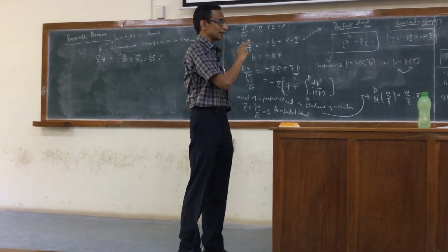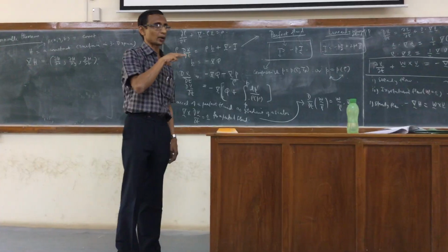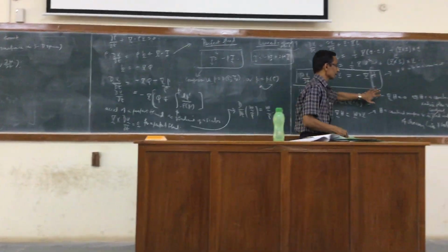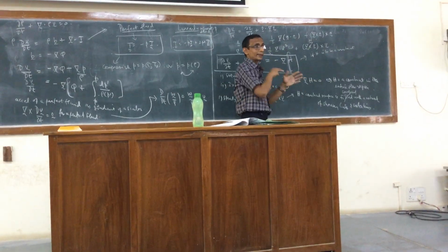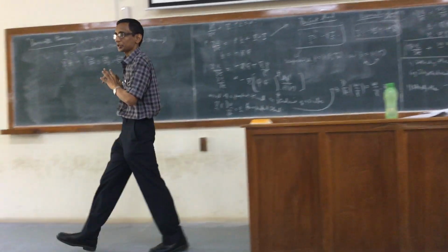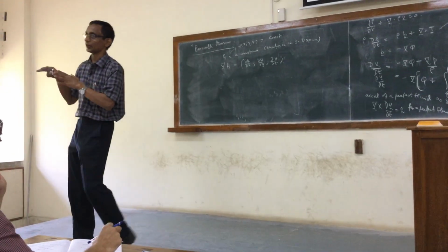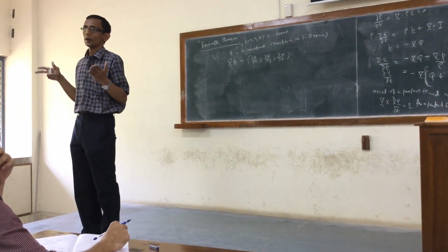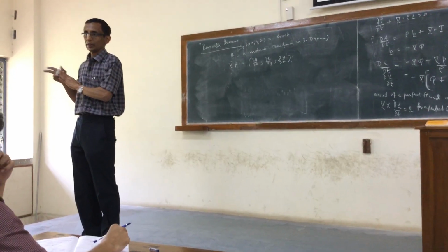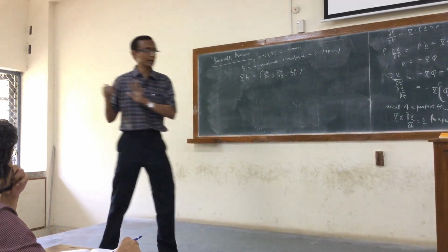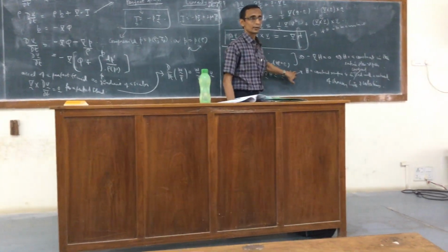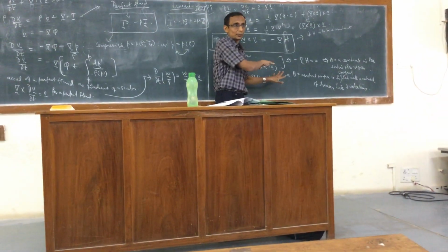So it is somewhat different. He's not yet saying that h is equal to constant along a streamline or a vortex line, unlike what we got here, right? The gradient there is identically zero; we're considering a slightly different situation. Impose the condition of steady and irrotational, and I get the gradient of h, the quantity h, is 0. Right? Here the gradient of h is not 0. Gradient of h is actually given by w cross v. So the flow is not irrotational.